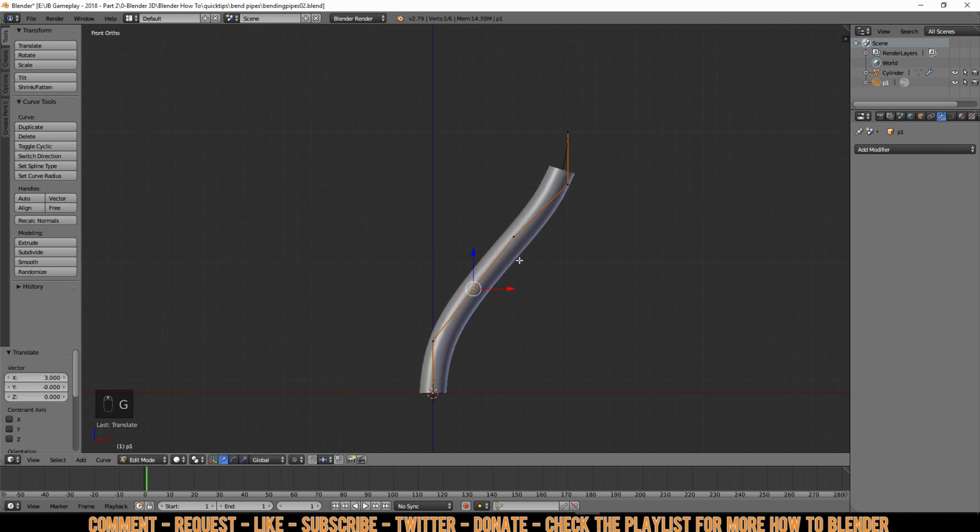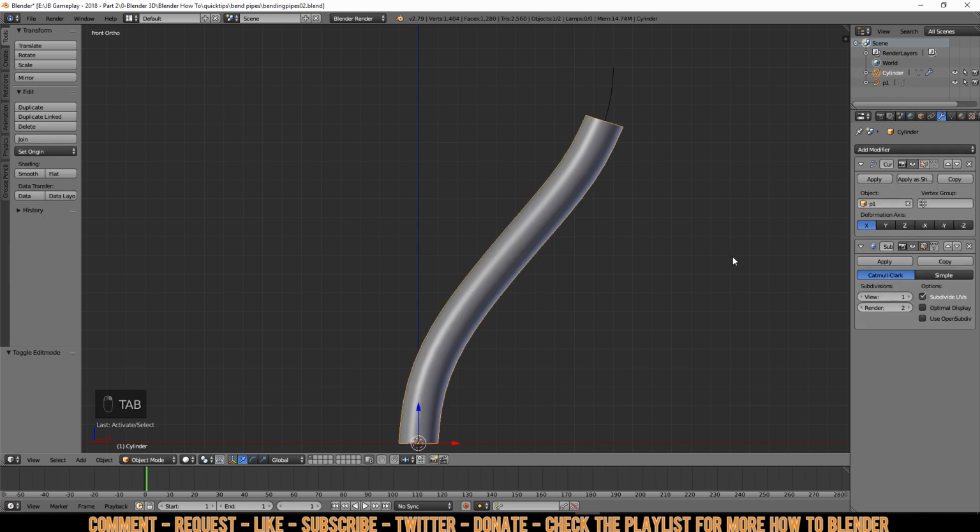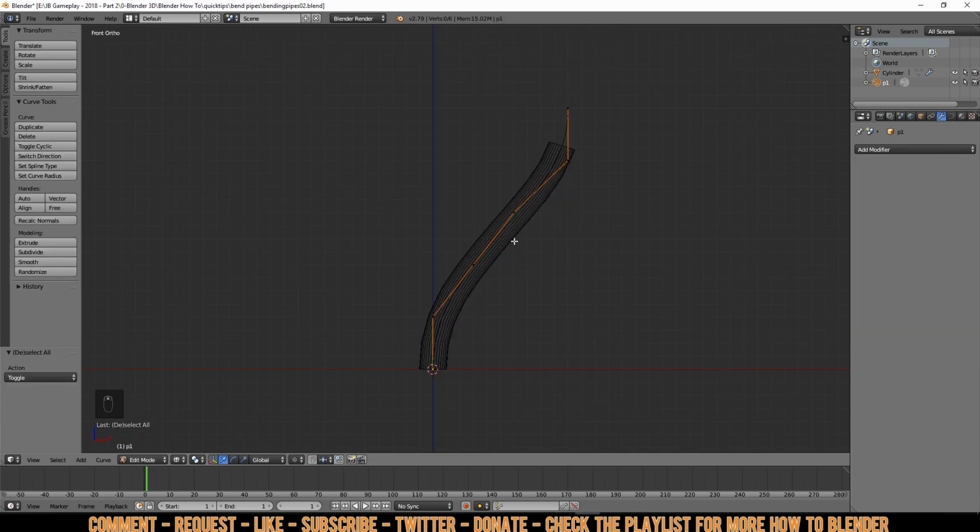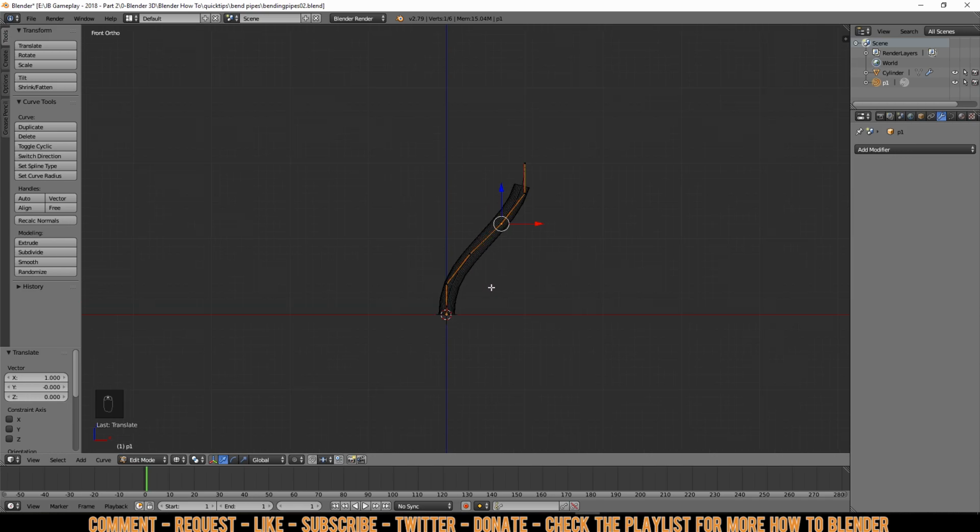Now if you want to have a better idea of what's going on, which in this case I mean the grid, you just turn off this subdivision surface, press Z for wire mode. I like to work on grid mode, so I've got this dot down here, 2 blocks off from this line, and I've got it 1 block off the middle. I'm gonna make it 2 blocks off the middle, which in this case I actually mean I'm just splitting this cube into half and calling that a middle line too. And I'm also gonna check out this one. It seems to be 2 blocks off this line, and it seems to be 2 blocks off from this line.